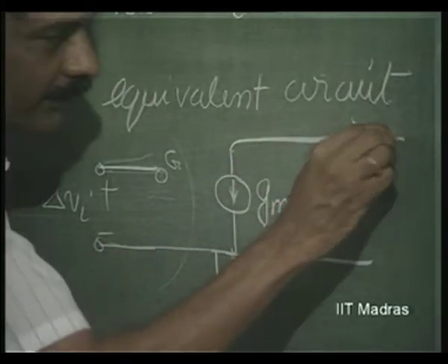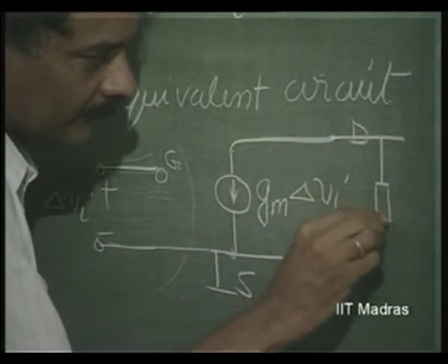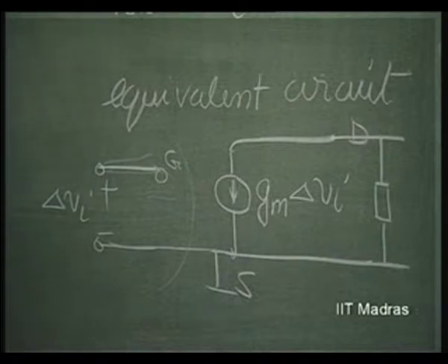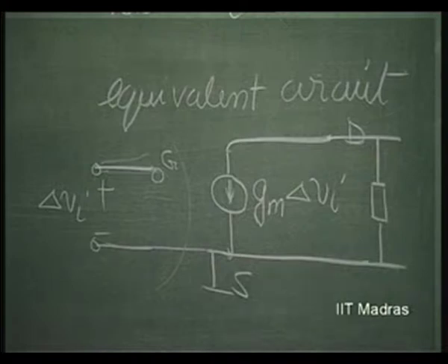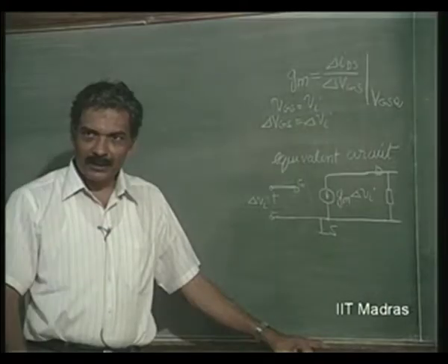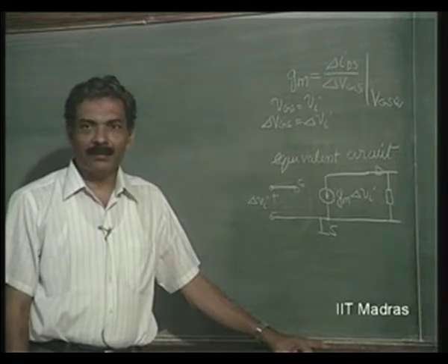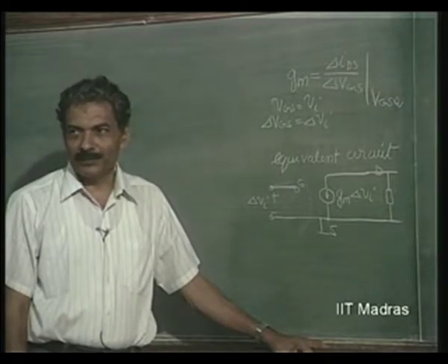At this point, once again just like the case of a transistor, we have the channel resistance not being infinity, not an ideal current source; the characteristic is not exactly horizontal, there is a small increase that we have explained in terms of lambda, if you remember.